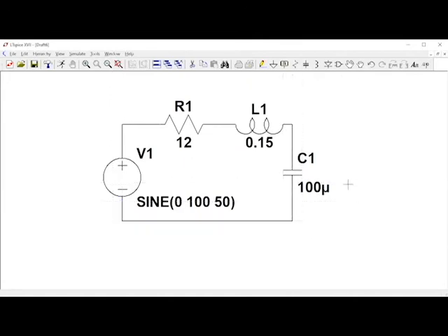If you messed up a little bit on this step, the Delete tool is useful here as well. Click on any unwanted wires with the Delete tool cursor active to delete them from the canvas. Finally, we're going to add ground to the circuit. Click on the ground icon on the toolbar or press G. Place your ground anywhere on the circuit's wiring where you want ground to be. I would recommend ground at the opposite end of the voltage source, under the capacitor. And there you have it, your finalized RLC circuit.